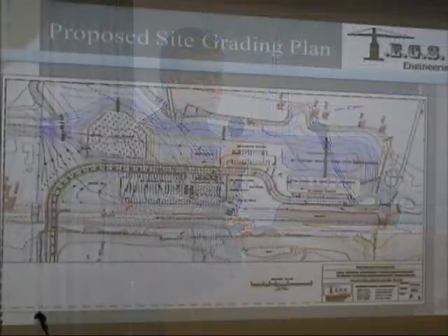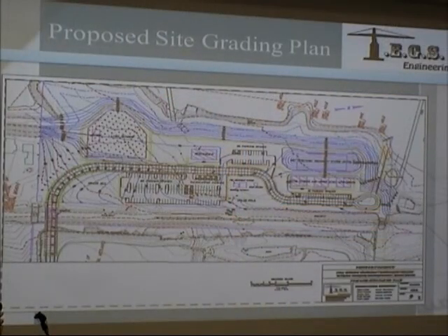Since our site is so low in elevation and we needed to build a bridge connecting to the existing road, which was at 64 feet, we had to go from 64 feet to a 22-foot elevation, which was for the retail and restaurant due to the 100-year storm requirements for FEMA. And because of that, there was an 8% slope on our roadway entering the site.